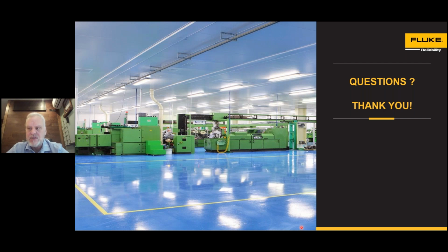Plus, in this case, the most important piece is that we are upfront during the startup phase of a program. We're adding very detailed machine information as opposed to some of the approaches that just add something very generic. That may work very well for a pump motor combination, but it may not work so well for a gearbox. If the diagnostic system doesn't understand your machine, it's going to give you very generic results and not very specific results. So our approach today is to be as specific as possible, and we do that by learning as much as we can upfront about your machines and continuing to evolve that process as we go, meaning as we find out more about the machine, or if we find out bearing information, all of that plays into the ultimate result that you get to help you make those ultimate maintenance decisions in your repair schedule.